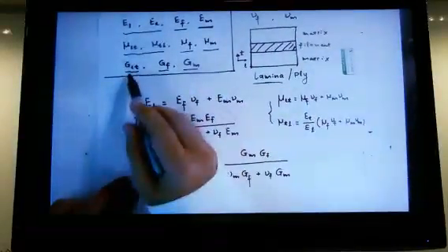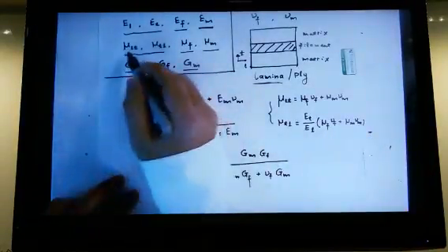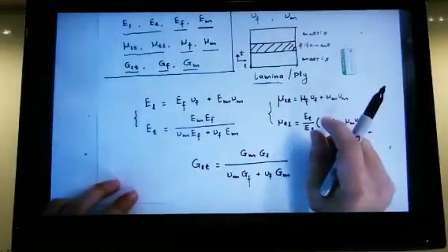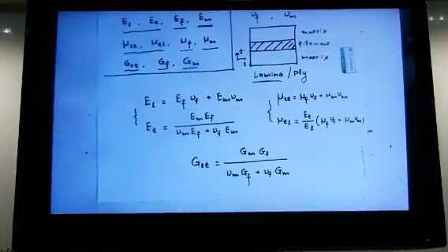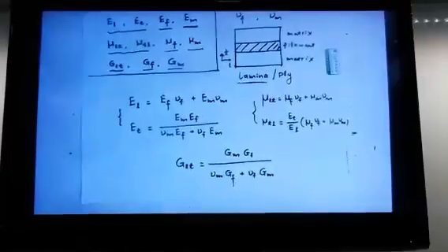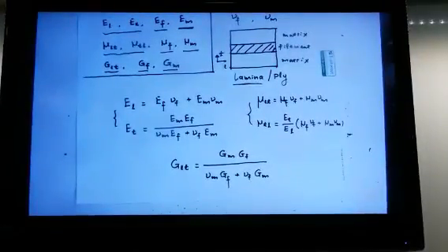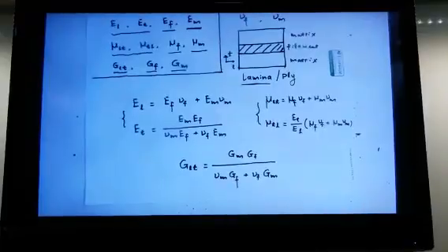In shear modulus, also when you have composites, you have GLT as the shear modulus, and mu LT and mu TL as Poisson's ratio. The definition of Poisson's ratio is when you apply a loading along one direction, you have a reduction along the other direction. So the reduction divided by the elongation, you get Poisson's ratio. When you look at the composites, the reduction divided by elongation along two different directions will be different. That is why you have mu LT and mu TL. But for isotropic materials, for fiber itself, or matrix itself, just one mu. Okay, mu F and mu M. Different material, only one mu, isotropic material.